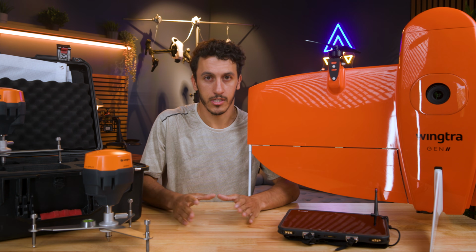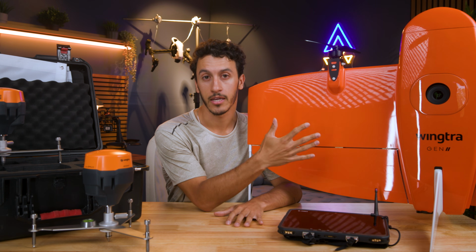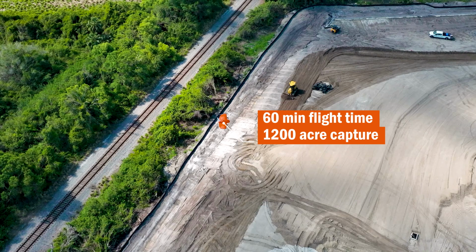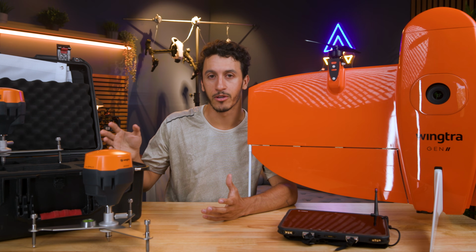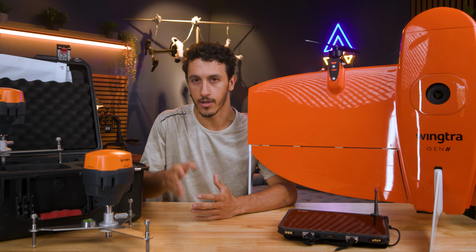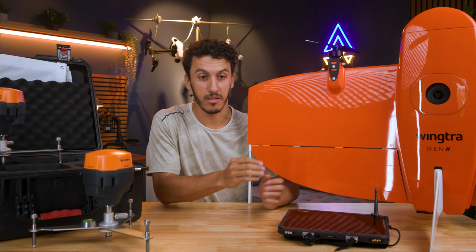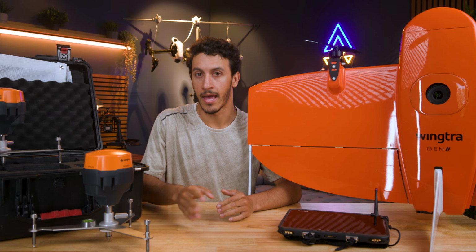But some key characteristics just to get that out of the way: the WingtraOne Gen II with their mapping payloads can get you about 60 minutes of flight time. You can pretty much cover about 1,200 acres on one flight at 400 feet, which is the legal altitude here in the US. And then obviously the Emlid Reach RS3, these are fantastic GNSS receivers. Yes, you get 22 hours of battery life in it, but again, the entire process has been made to be a 3-4 step, basically clicking some prompts on the screen and collecting that centimeter level accuracy out in the field.